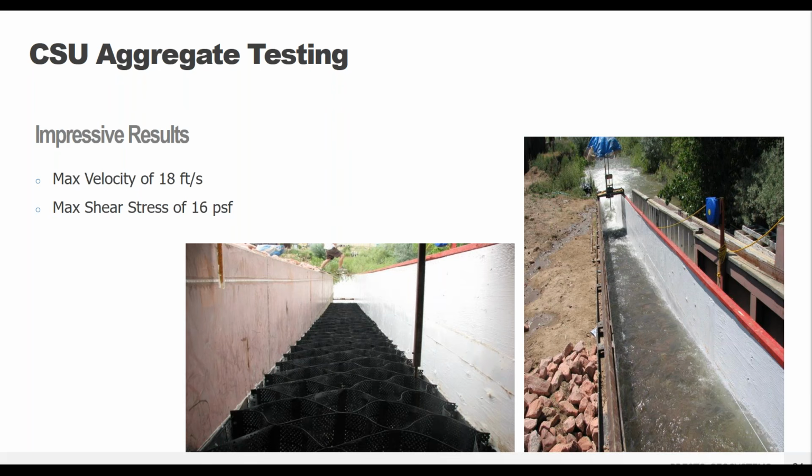So this might seem counterintuitive, but you have to think about it like this. You have the strength of a properly rooted full grass lawn compared to a single stone. And that's really what you're comparing, is how well does all of that soil stay in place versus what flow can it withstand before a single stone gets picked up and washed away. So that makes it a little more understandable as to why the velocity would be lower for a stone infill, because you're not considering it as a whole, you're considering each individual stone particle.